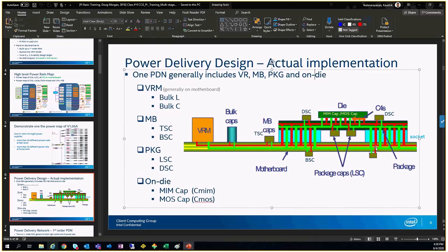Then we form ports on the top side of the package, which are called bump ports. These bump ports are where you hook up your die collaterals, which we had discussed in the previous calls with Prasad, where we were looking at the sub-circuit of the die given by the vendor. So this is where you hook up the die collateral and all the die collaterals.